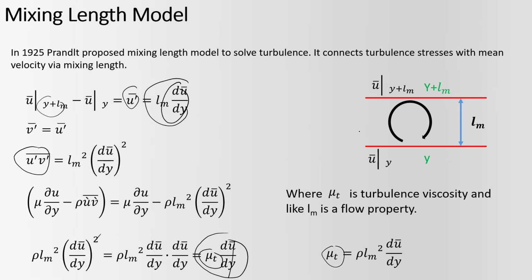So we found the various turbulence models, and we are after this term. Once we get this value, we can put it back into our original equation. So now the game is that we have to find this term. This term is from the mean equation that is already known to us at that solution step. So we have to find the mixing length and put the value there, and we will end up finding the turbulent viscosity.